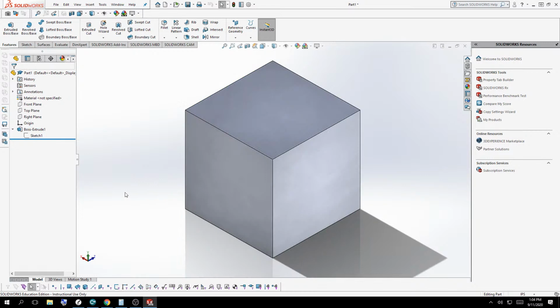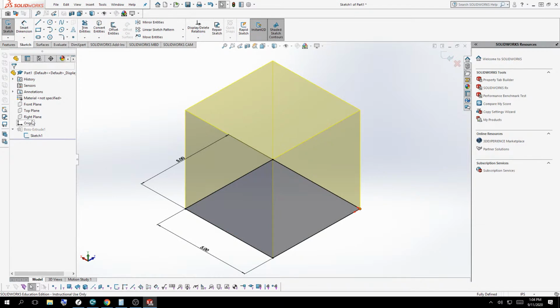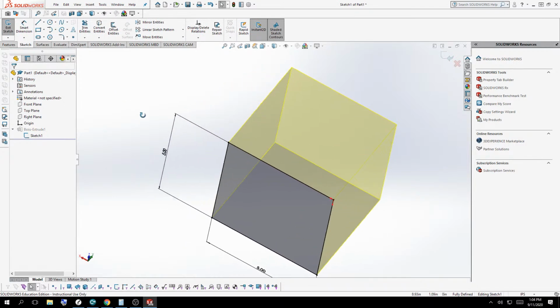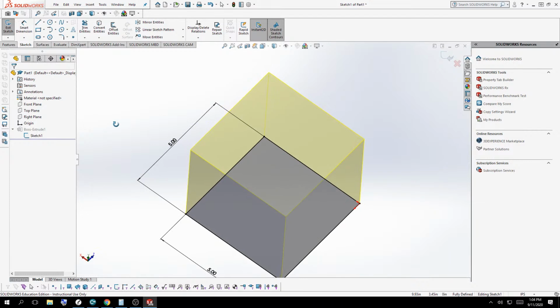But if you want to edit the drawing per se, if you click on the icon of the drawing, a little pop-up appears here. You get a bunch of quick commands, and if you go to the upper left-hand corner, you can edit the sketch. Ignore the yellow that you see, but the 2-dimensional sketch is still there. And you could then go ahead and add additional geometry, trim it, cut it, put additional holes in it, or so forth. Don't do this, but this is just a demonstration.